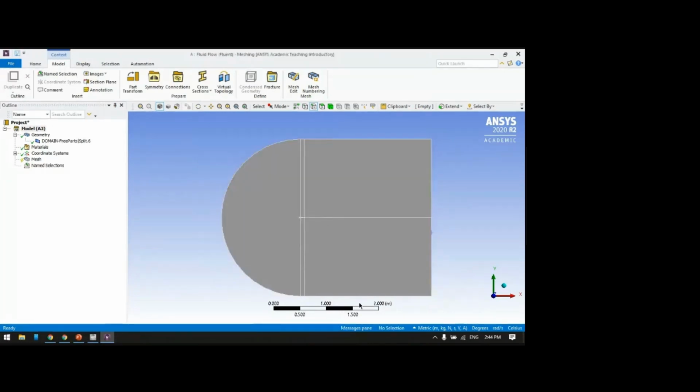And I'm going to take the complete thing as the inlet. Some people will define this as inlet, this is wall. Okay, so if you are going to take this as wall, then you cannot go for this inclined injection because here you define the wall. If you are defining the flow in this direction, then from the wall there will be a disturbance. Okay, so if you are going to keep only one domain, and simply for changing angle of attack, if you are going to change the velocity component, better make the complete line as the inlet.